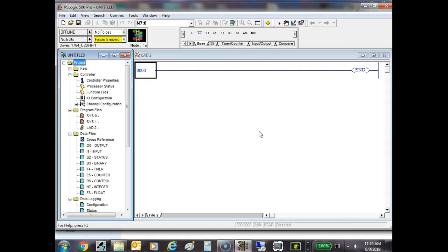Okay, now I'm ready. And we want to create a program. So what we have is a bunch of input modules. And this is a fixed PLC. So the first module number on this is a fixed PLC. The CPU does not take up a module number. So my first module number available is module 0. Y'all follow me so far?